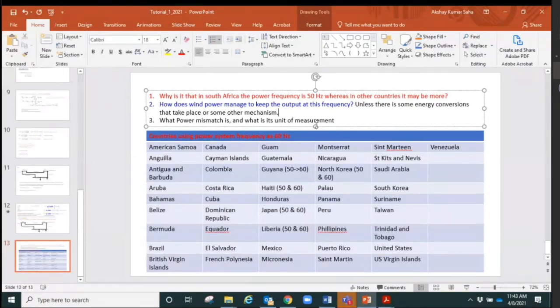The same thing happens in a wind turbine as well. The inertial effect is there. That's the first part, mechanical. We don't have to do much, but we need to control that part. For controlling, in a thermal power plant, hydroelectric power plant, or gas turbine power plant, we put a governor that responds to that frequency to control the input mechanical power to the system through water, steam, or the gas input to the gas turbine.